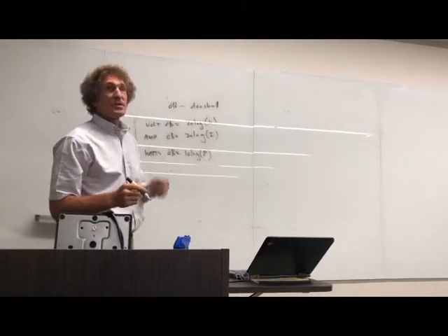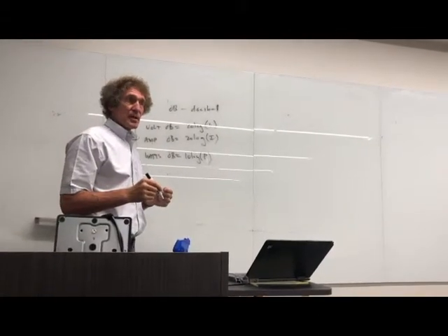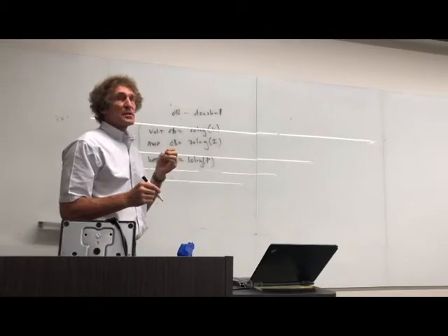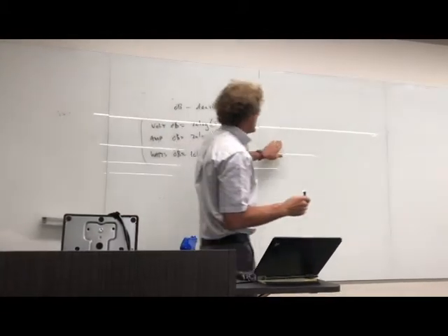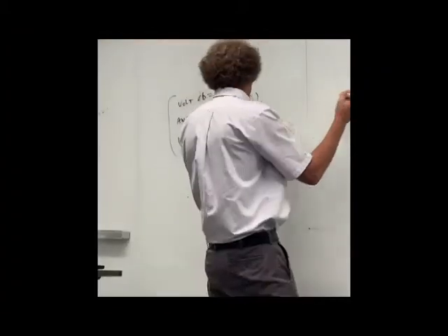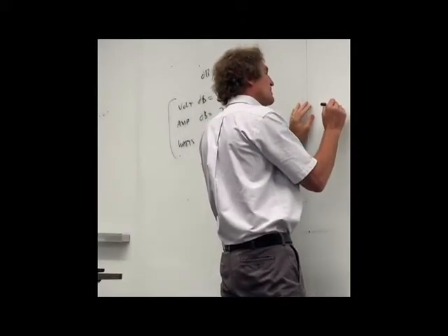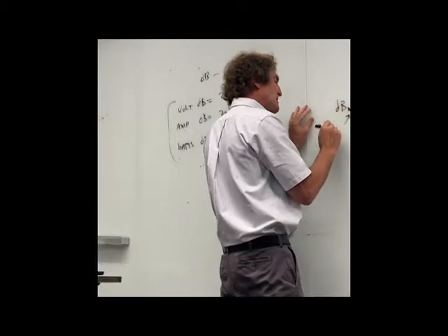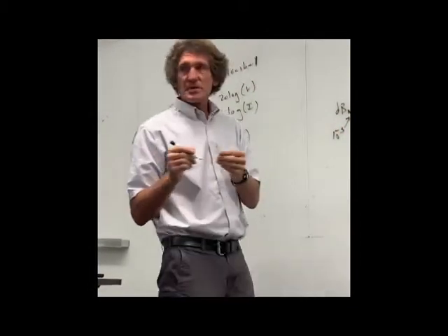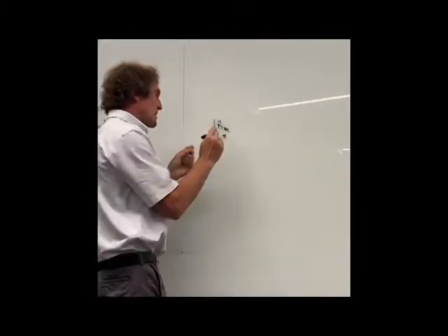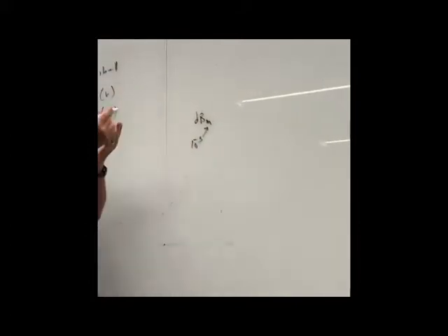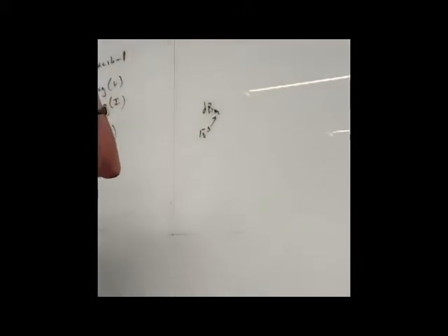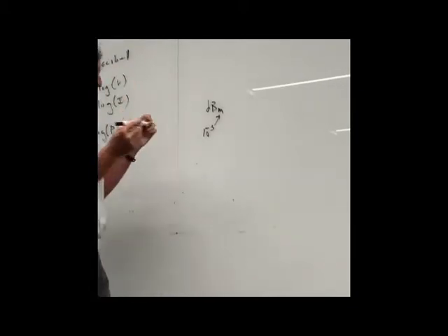Now, specifically when we talk about decibels, there are some units of measurement that are common. One is dBm, and that's for power, it's the most common. The m indicates 10 to the minus third, a reference. So dBm is decibels using a milliwatt as the reference.